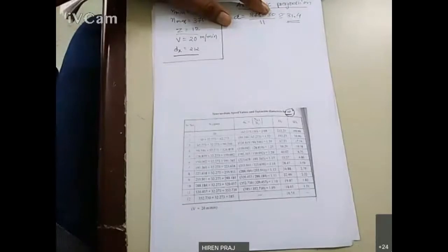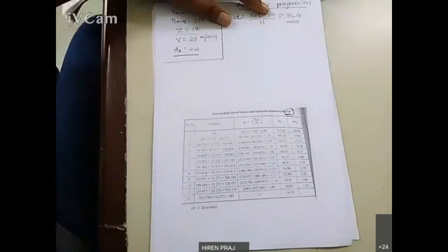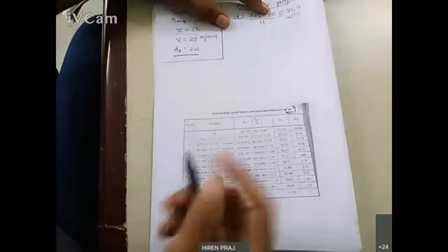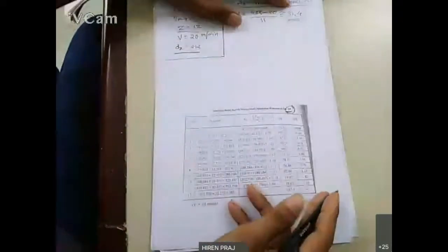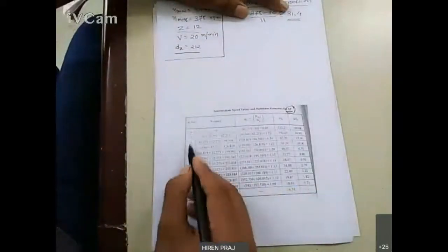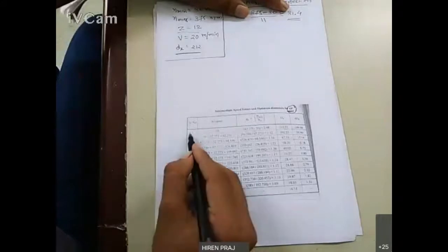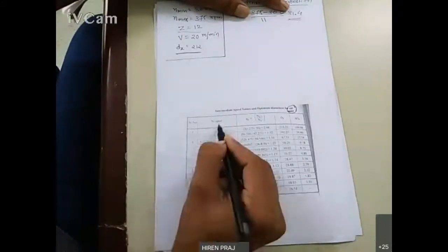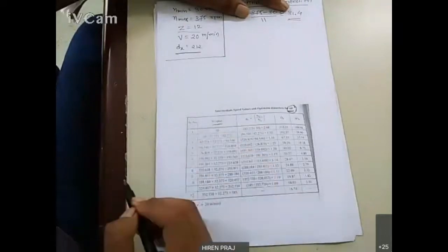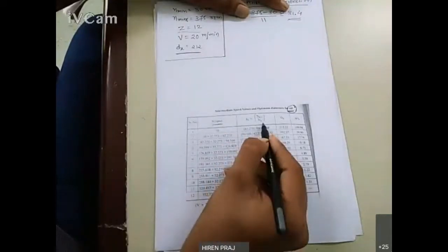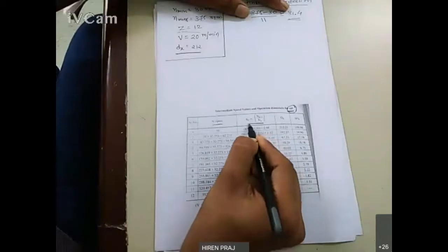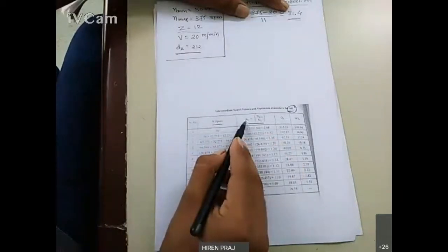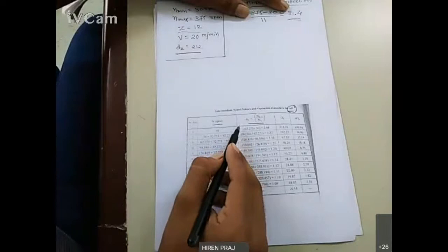So if you look in this table, I hope it is visible. In this table, as I told you, we want total 12 speeds. So in this table, this column indicates the number of speeds. This is the value of each RPM, and this is the phi, the speed ratio between two speeds.